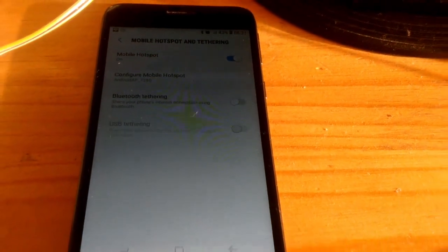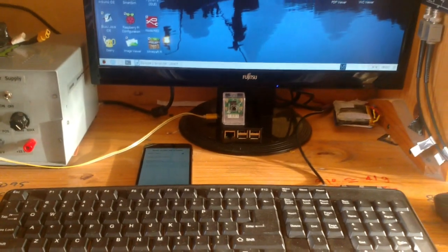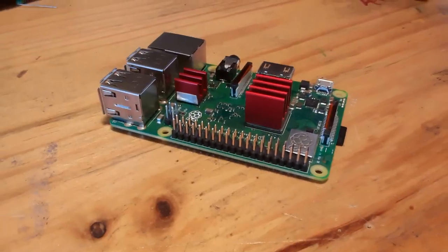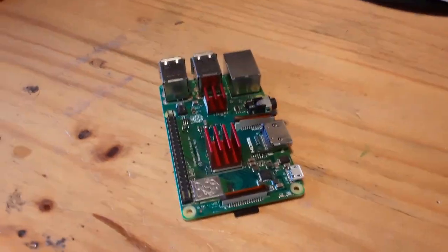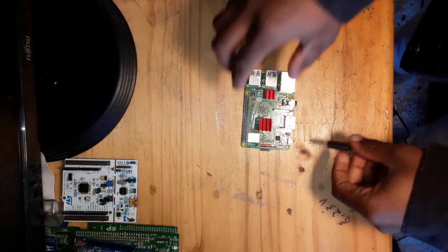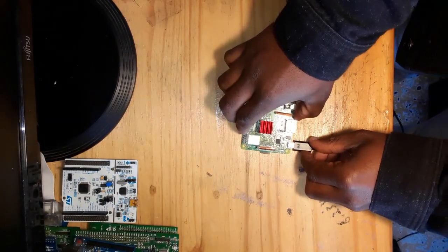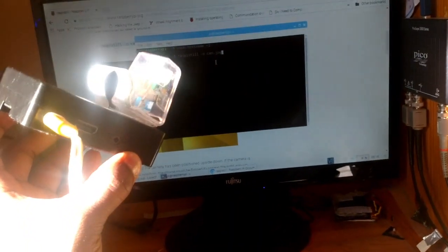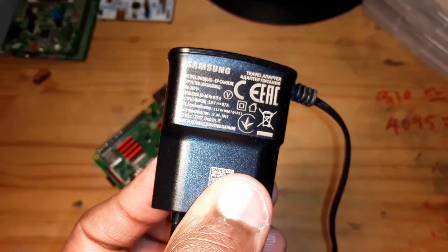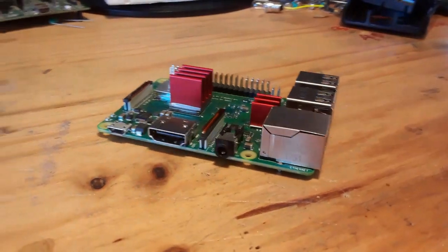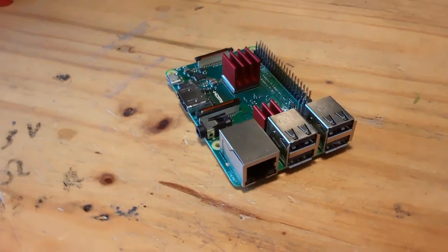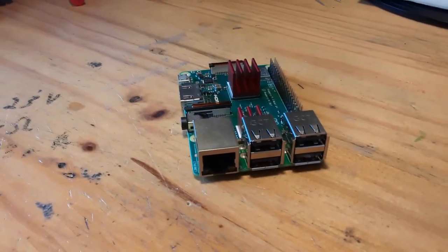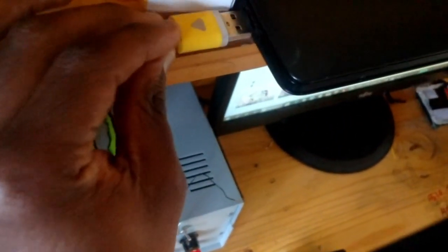In this series, I'll be making use of the Raspberry Pi 3. The Raspberry Pi 3 is powered by a 5 volt micro USB supply. Exactly how much current the Raspberry Pi requires is dependent on what you connect to it. It is, however, recommended to purchase a 2.5 amp power supply from a reputable retailer for sufficient power to run your Raspberry Pi. I, however, use my laptop's USB ports to power my Raspberry Pi, typically USB 2.0.